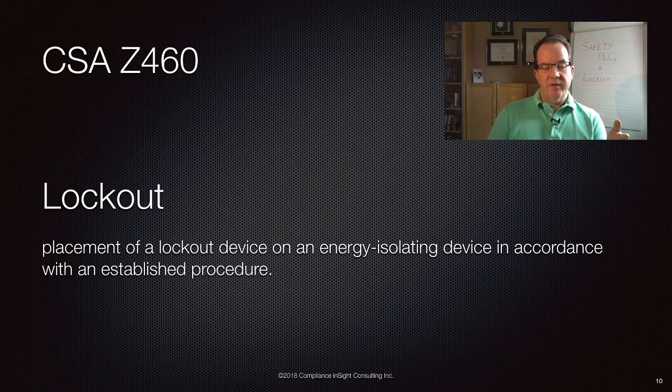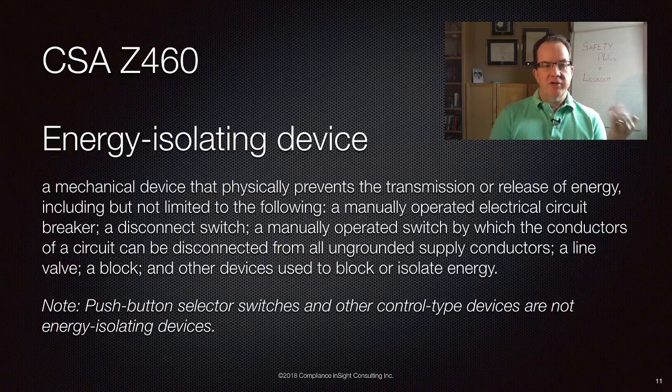So to really understand what this is about, we also need to look at the definition for an energy isolating device. An energy isolating device is defined as a mechanical device that physically prevents the transmission or release of energy, including but not limited to the following: a manually operated circuit breaker, a disconnect switch, a manually operated switch by which the conductors of a circuit can be disconnected from all ungrounded supply conductors, a line valve, a block, and other devices used to block or isolate energy.